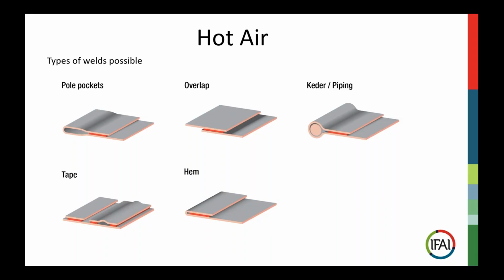Now, what's tape welding? It can come in many different facets. You can weld reinforced webbing to strengthen a structure. You can use it for waterproofing, in essence covering up stitch seams, say, with polyurethane coated apparel, or even acrylic. So acrylics aren't weldable themselves, but using a tape in between the two layers of acrylic can bond those with hot air as well.